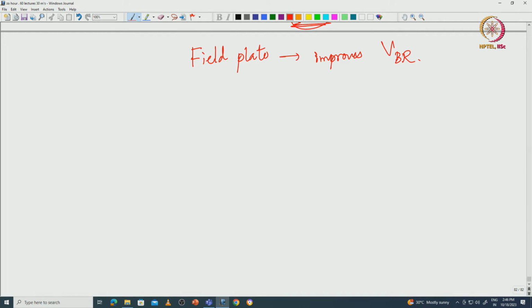But before field plate, there is another very important and most crucial part, which is passivation. You need to passivate AlGaN GaN HEMTs, and this passivation is almost always universally done using silicon nitride. Although academically people have researched other dielectrics also, high-K dielectrics, silicon oxide, aluminum oxide, and many other materials, silicon nitride is the one that is most widely adopted and also used in industry. Silicon nitride passivation is extremely critical for realizing and developing practically relevant AlGaN GaN HEMTs. Okay. And this is because it helps prevent or mitigate current collapse.